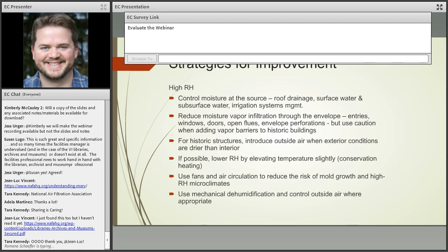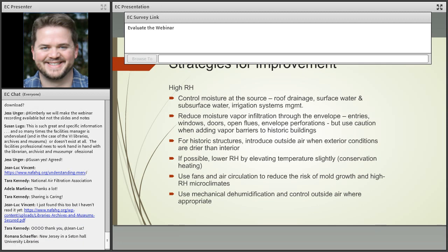It's one of those situations that if you can get into your system controls, if you have this capability to dial back the outside air quantity overnight and reduce the moisture that's being brought into the building when you don't need the fresh air for occupation, that can give the system and the environment a little bit of a chance to catch up in terms of being able to dehumidify more effectively for that 8 or 10 or 12 hours, depending on your building schedule. And then recognizing that when the people are back in the building, you will certainly need to open up the outside air intake again for occupation. And you're going to reload the space when it comes to moisture, but it at least should give you some chance to recover during that overnight period.